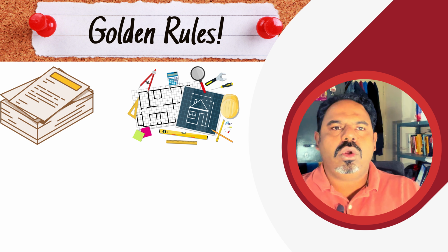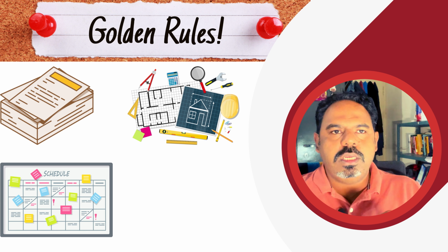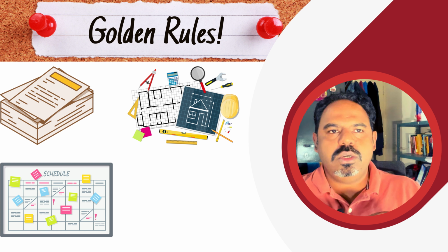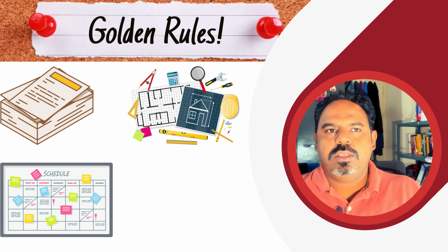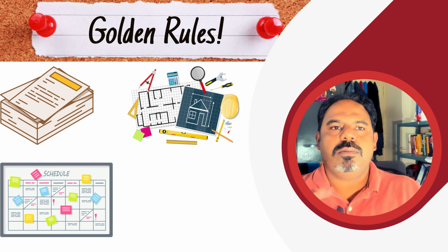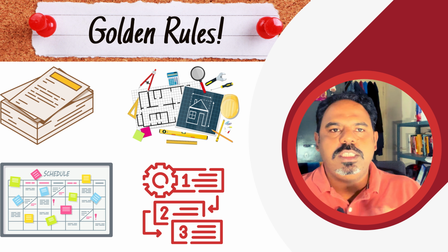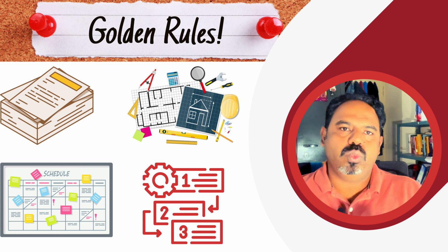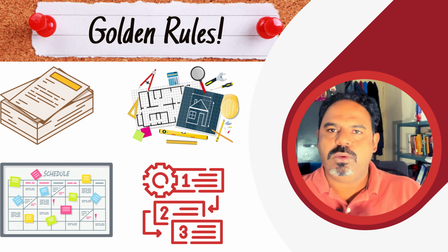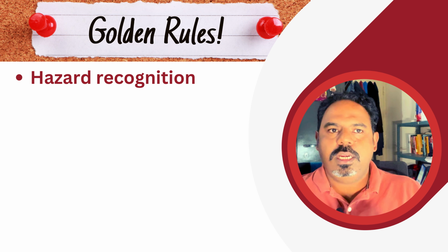The HIRA team should also be aware of the project schedule and timeline and should remember that risk management is done to work safely, not just implement safety. Safety must always accompany work progress and vice versa. The sub-activities must be sequenced in the same way as the work method statement of a particular activity. While recognizing hazards, try to cover all phases of hazard.